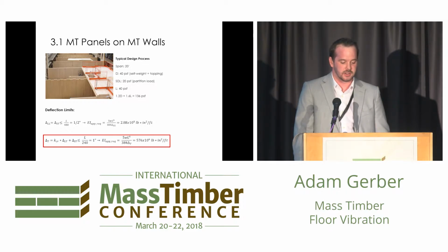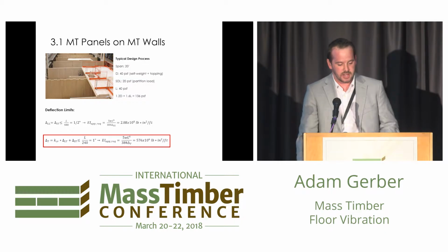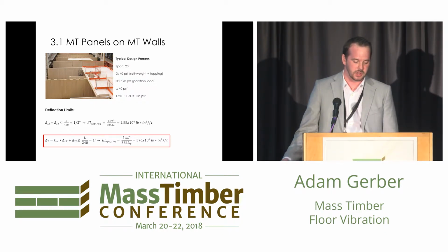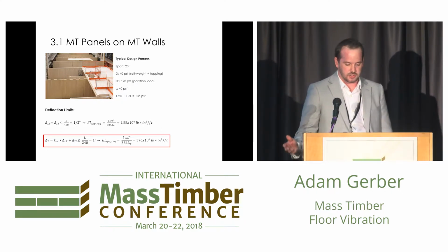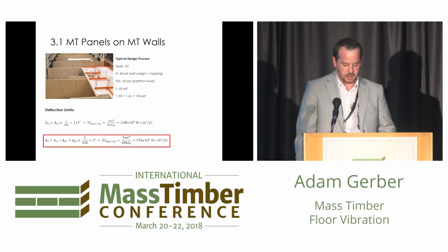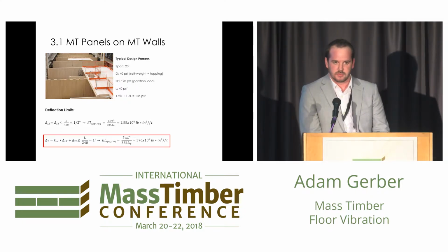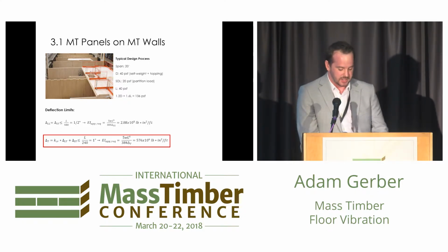of a mass timber vibration and typical design process, to illustrate where you can potentially run into problems. So in a case where we have mass timber panels spanning between mass timber or lightwood frame walls, or whatever the walls may be, in this case I chose a 20-foot span, typical concrete topping and typical live load. So I went through and picked a panel based on the deflection requirements, because we do know, and we hear often, that mass timber is governed by serviceability.